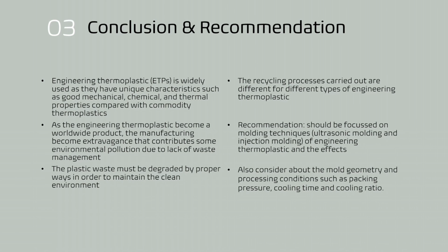For recommendation, it should focus on molding techniques such as ultrasonic molding and injection molding of engineering thermoplastic and the effects. Also consider the mold geometry and processing conditions such as packing pressure, cooling time, and cooling rate.